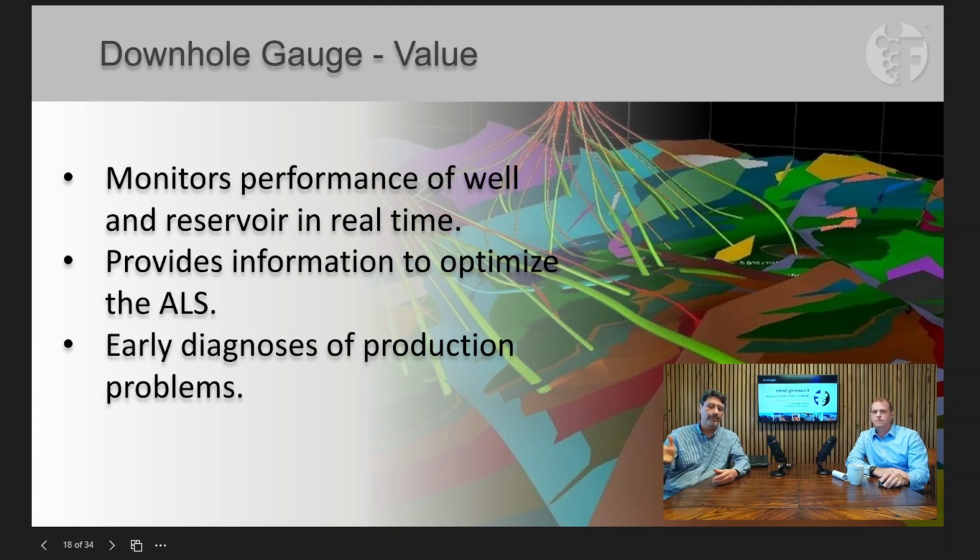So they ran some characterization of those issues with that data, and they were able to see when a pump was starting to give up, or there was a lot of gas and stuff like that. So they start adjusting and preventing issues, or if the issue was not preventable, then a scheduled rig intervention with time, so they don't have a lot of deferred production because the well is down. That makes sense. So in your pump applications, you can use that vibration piece of the gauge to recognize how efficiently your pump is running. Correct, and that's really helpful.